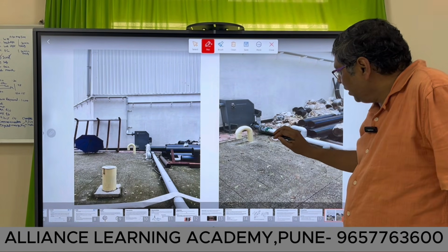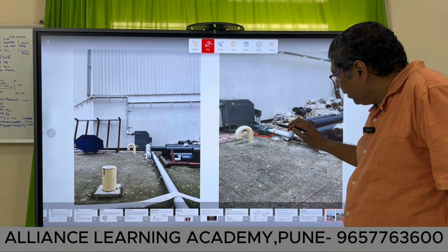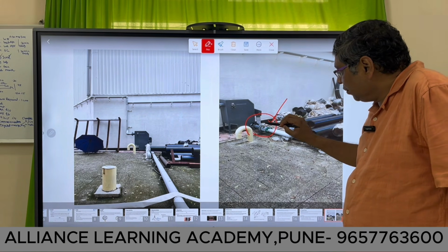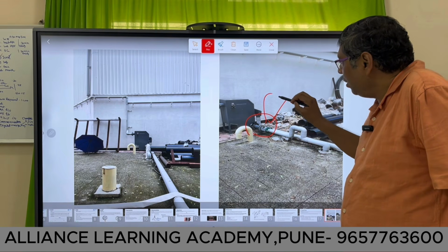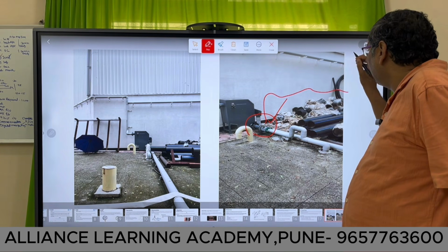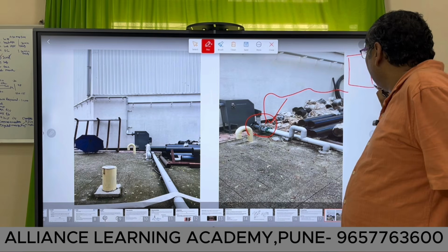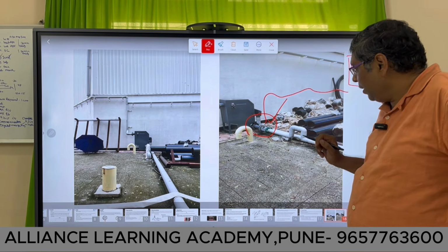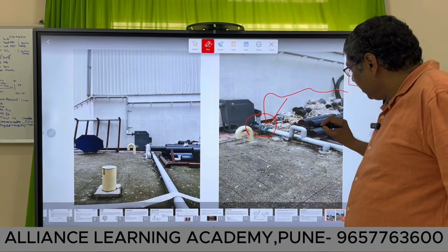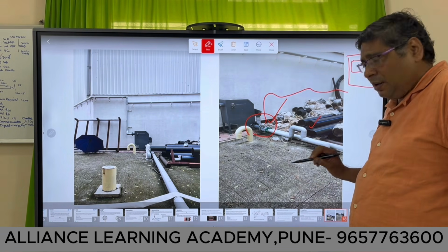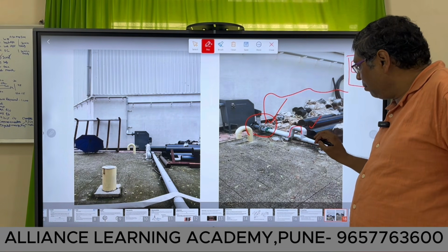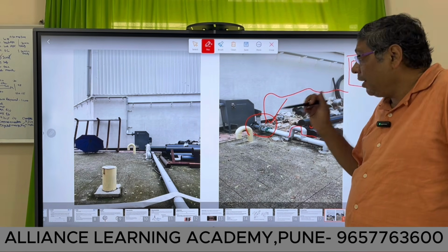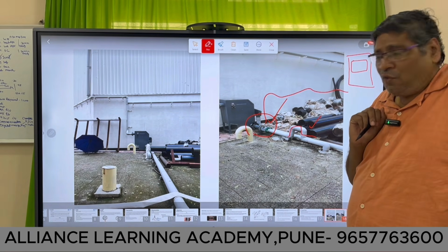We are seeing one electromagnetic flow meter. This is the remote type, meaning the junction box is here and by the cable it is connected to a converter, where readings are coming. Now you see the important thing is the installation. It is like an inverted U, made to keep the pipe full every time. But here they made a mistake. What mistake did they make?